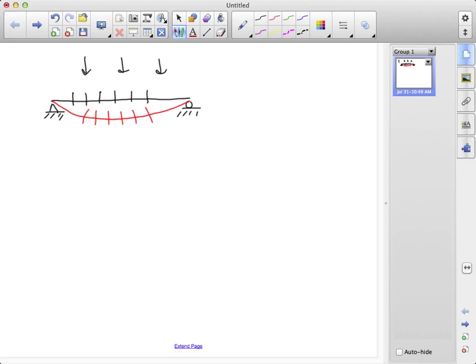This is where our reference to rotational resistance presents itself. An area moment of inertia provides the resistance offered by adjacent cross sections to rotation with respect to one another. If we draw lines through the rotated cross sections, they eventually meet at some point. Thus, at every position x along the beam, we can define a local curvature, kappa of x, and its inverse, a radius of curvature, rho of x.